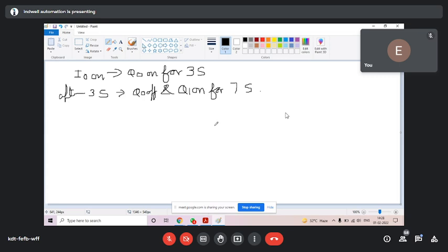You ask your question once more, please. Yeah, so my question is, the moment the input to the timer is off, the output goes off. If you have taken output from the timer done bit, if your output is on from the timer done bit, then it will be off. So you have to see whether your output is getting signal from the latch or from your timer. If your output is getting signal from the timer, then it will stop, obviously.